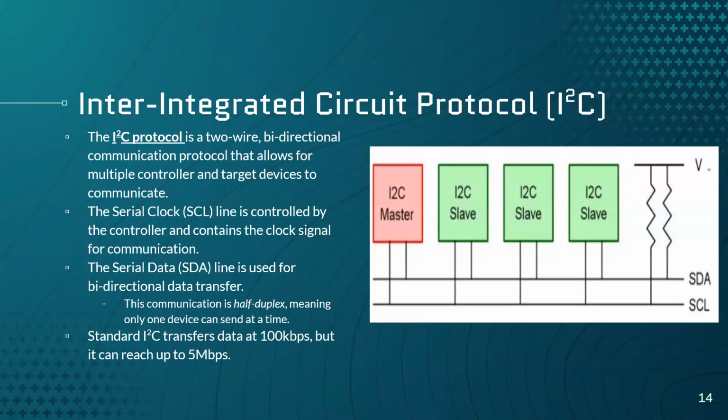Cool. So that's why when I say the master, the main device grounds it, you're seeing that change from a 1 to a 0. And then you can start getting your communication. Because then all of the secondary devices know that communication is happening, because they are still connected to that line, so they can still see that information. They'll see the 1 change to a 0. They'll know to look for that, and then they'll know to see, oh, now it's going to be sending a command. Oh, device 1, I need you to send your information.